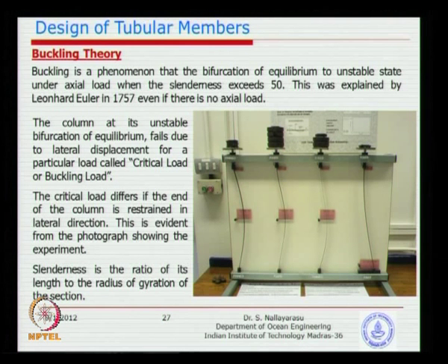You could easily visualize that if it is a free end at one end and fixed at the other end, it carries lesser load than both ends fixed, and vice versa. We call it the effective length. Basically if you look at all four sets of diagrams in the experiment, you could see one of them carries a very heavy load for a typical lateral deflection of some amount, whereas if you look at this fixed-free, it carries only a very small amount.